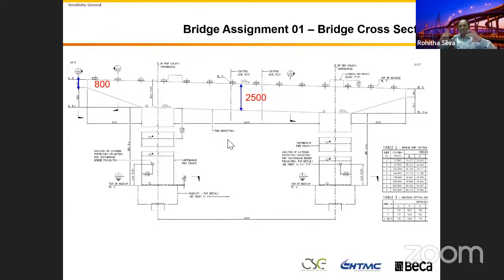You can use a simple calculation to get the girder reactions, or else you can run a grillage model or a simple bridge model. We do that in the concept design stage. If you want to estimate the cost, you need to give your estimator the steel per cubic meter.